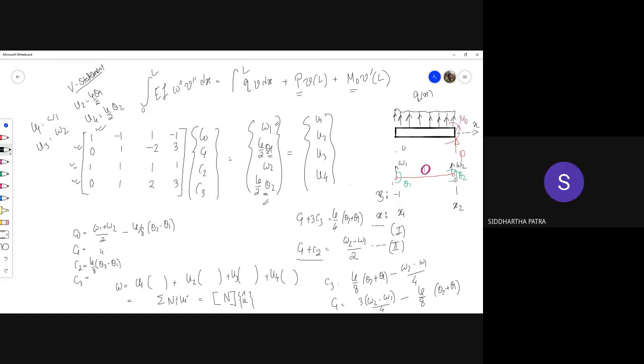You see these Ci's are the coefficients, and we just figured out, satisfying some boundary conditions, that they could be represented in terms of Wi's and thetas that we have already done. So there is C0, there is C2, there is C3 and C1. But then if you substitute C0 through C3 in the expression of W, where it is a cubic function of xi with Ci's as the coefficients, from there you will get a representation involving the polynomials of xi and Wi's and thetas.